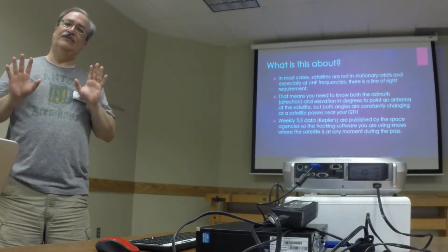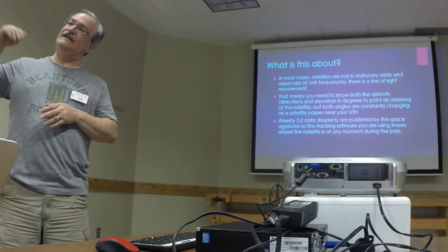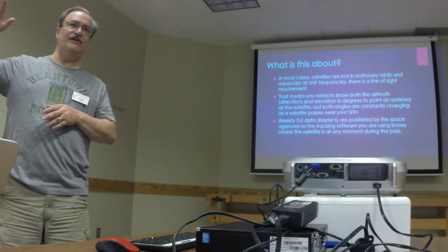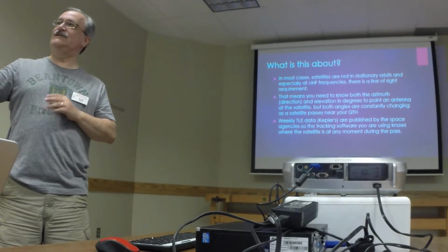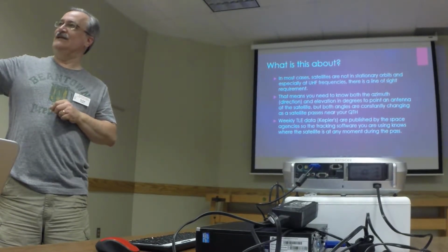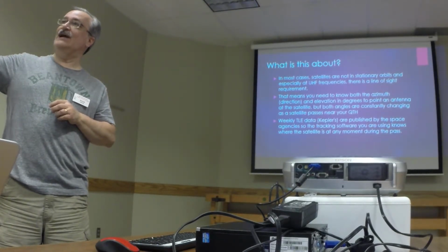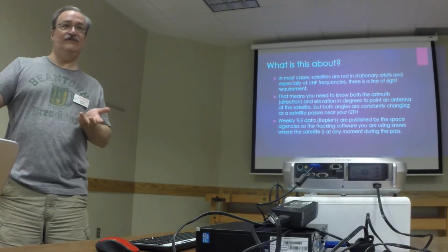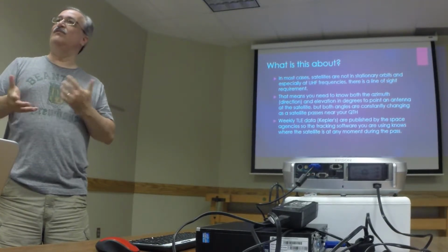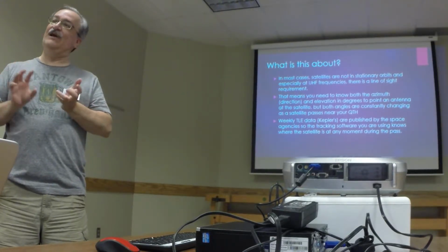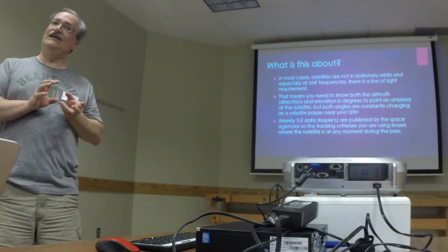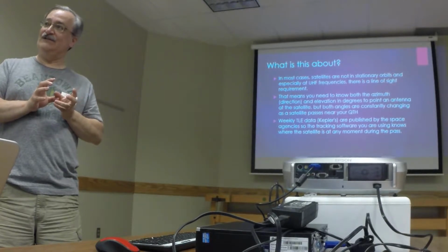But if you want to point your elevation up about 30 degrees and then just rotate, that's not too bad because you can rotate the rotator manually and kind of track the satellites, and that's what I was doing for a while. The trouble with that is that you also have to manually, unless you have rig control, do the Doppler shift.